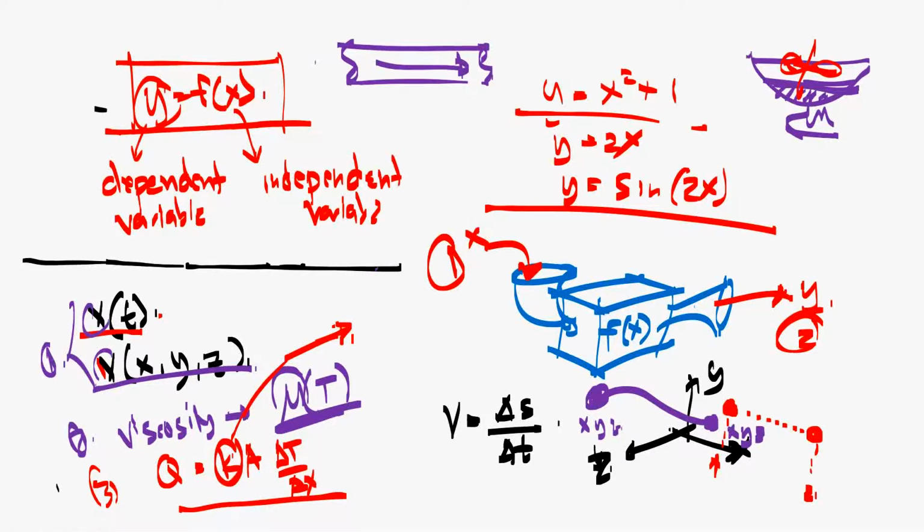How much heat is a material able to conduct? Some materials are insulative in nature, meaning they don't allow much heat to conduct, or they retard the flow of heat. In a heat transfer course, we assume that this is constant. For a specific material, for example polystyrene, the value is taken as a constant. However, for some materials, like liquids or gases, k is a function of temperature, or sometimes k is a function of pressure.